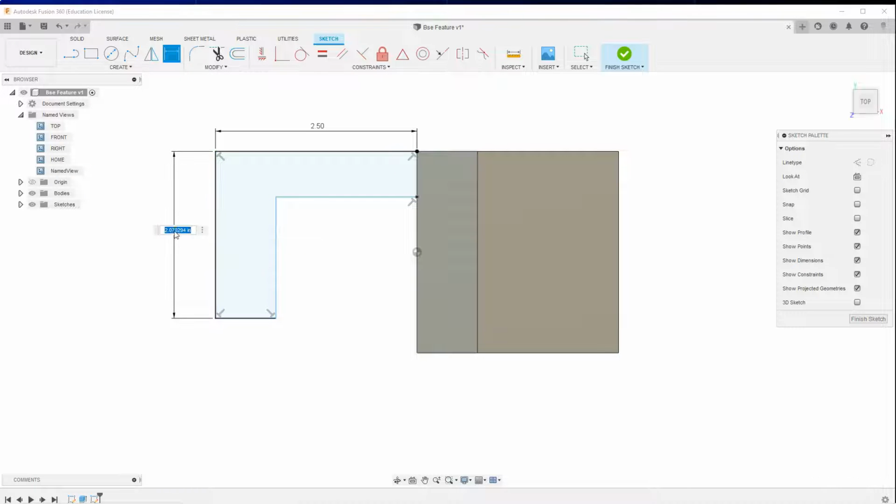So when I select this, I can type in 2.5, or I can just go up to this dimension here and select that dimension, which is 2.5. So that would always be equal to that. But that would be only in the case that we always want that to be equal. So I am going to just change this manually to 2.5.